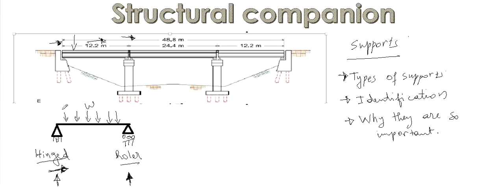So if there is some horizontal load applied, there can be a horizontal load applied on the bridge, in this direction. This horizontal load can be, for example, the brake load, when the car is moving faster and it brakes, this load can be estimated and applied on the bridge as a horizontal load, and you have to determine how much it is so that you can design correctly your support here.